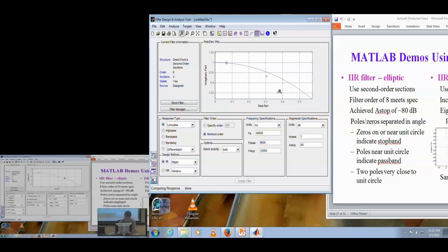That's very close. Go ahead. For sanity's sake, could you remind me what is the effect, just in general, of a single pole on the response of the system, like the effective response? Right. So remember, the pole impacts the denominator of the frequency response, and so to evaluate the magnitude of response, say at this frequency, it's 1 over this distance to the pole.